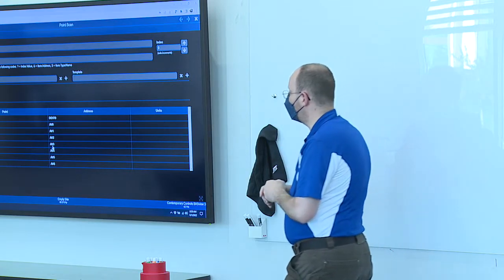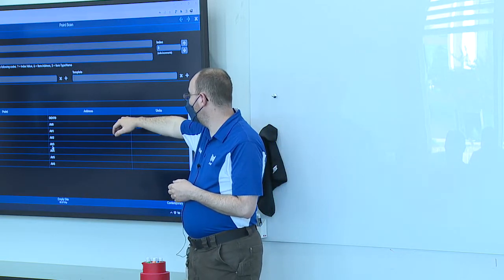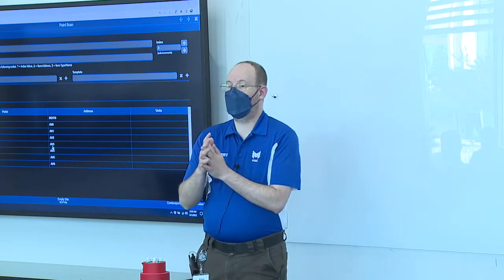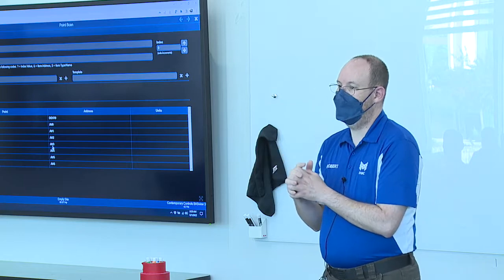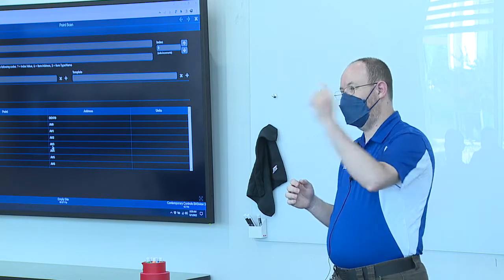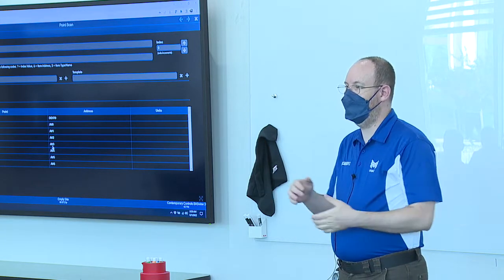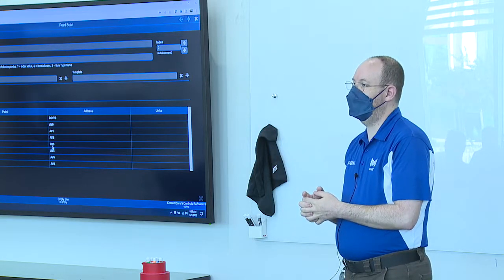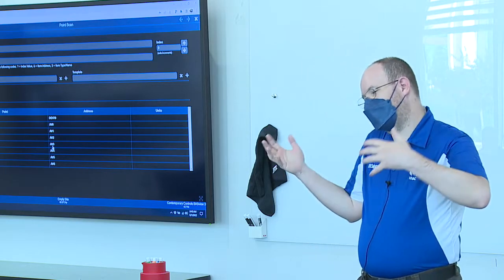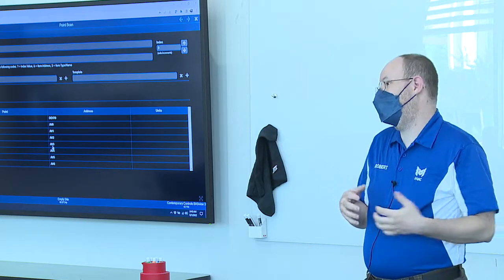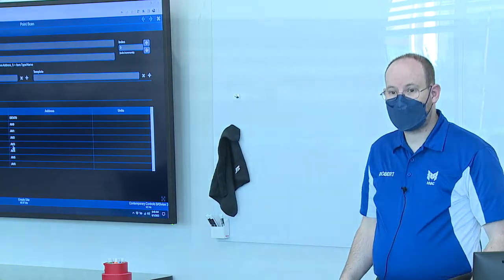With the air handler controllers, like I said, you should catch about 257 points. The first one is going to be the air handler's name itself. After that, you're going to get 128 analog values and 128 binary values. This is one of my pet peeves with the EasyIO controllers, is even if you haven't used an analog value or set it up, it still pukes it out onto the network. I think it's lazy programming. And the guy who wrote that part of it, I've talked to him, and he's like, yeah, you're right, it was lazy. Okay?